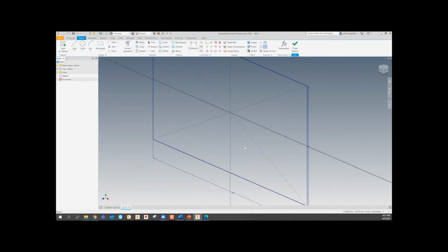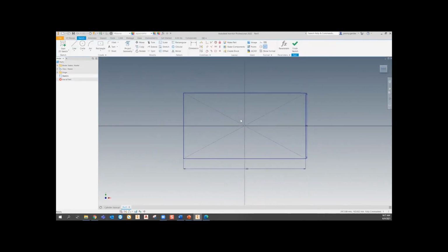Let's go back. I want to go with one thing I always forget. If you're having an issue with a particular sketch, if you're trying to extrude something or do something and it's saying that the sketch is not a closed profile, closed loop, if you right click, you can go to Sketch Doctor, diagnose the sketch, and these are the things that it's going to look for.